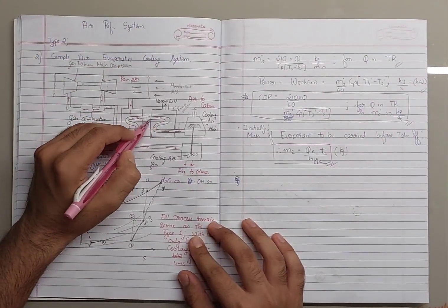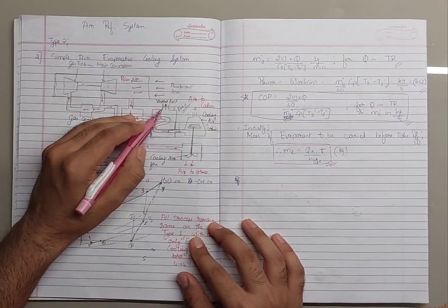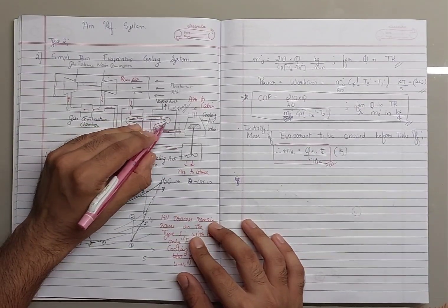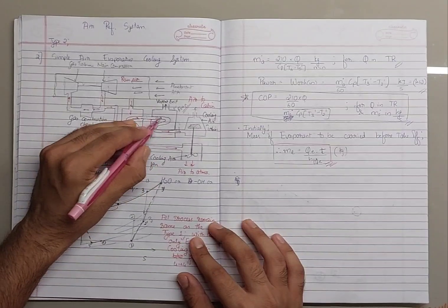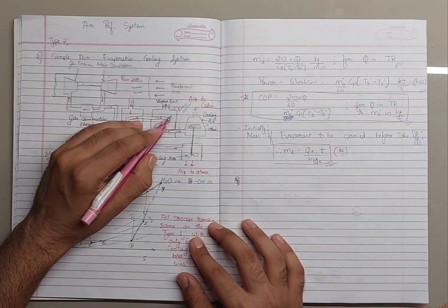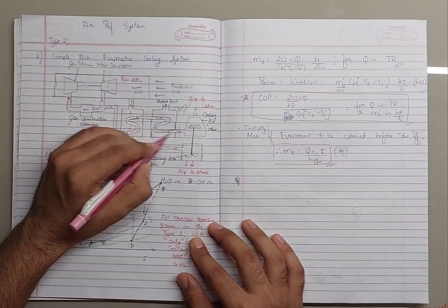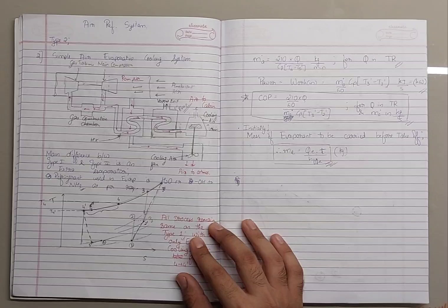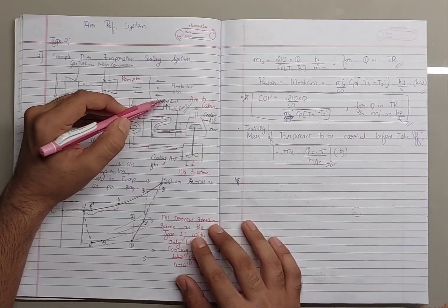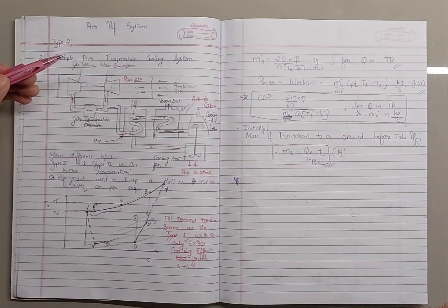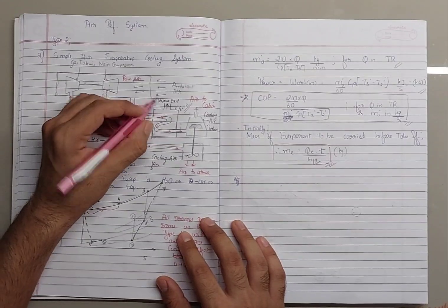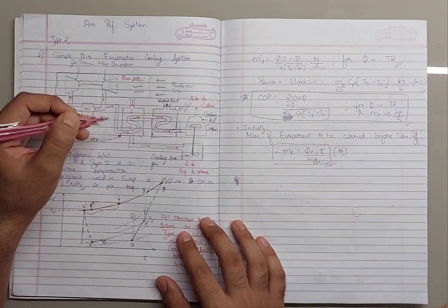The evaporator contains an evaporant. This being an open cycle, the evaporant accepts heat energy from the passing gas, that is air. We have air into the system. So the evaporant present inside the evaporator accepts the heat of the gas and it evaporates. As it evaporates, it exits from this outlet, and this being an open cycle, the vapor form of the evaporant is diffused into the ambient. So over time, as the process takes place, the level of the evaporant decreases.